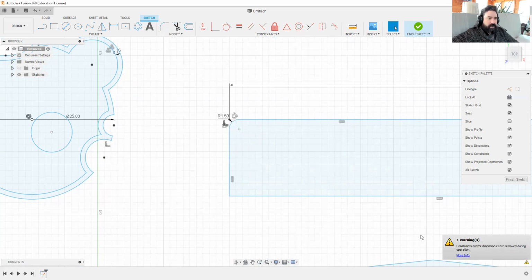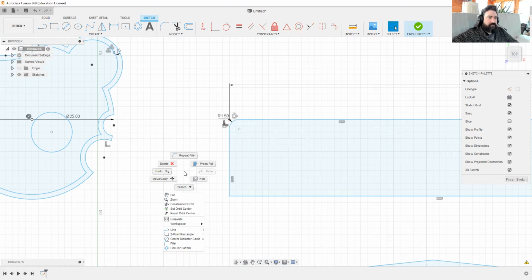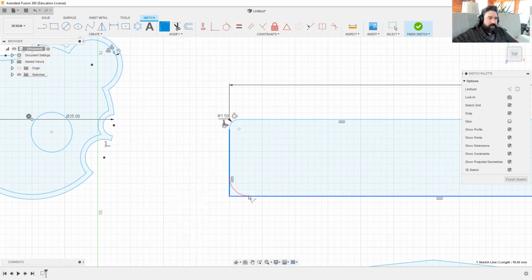All right. Yes. Warning, I changed that. I get a couple constraint icons that those are now working off of a tangent. That's the tangent icon, but we'll talk about those at another point. I just want to focus on the line tools. Now I can repeat that fillet. Yes, I can keep going up, clicking fillet, or right click, bring up my recent toolbar, go up, and now I can do the same.